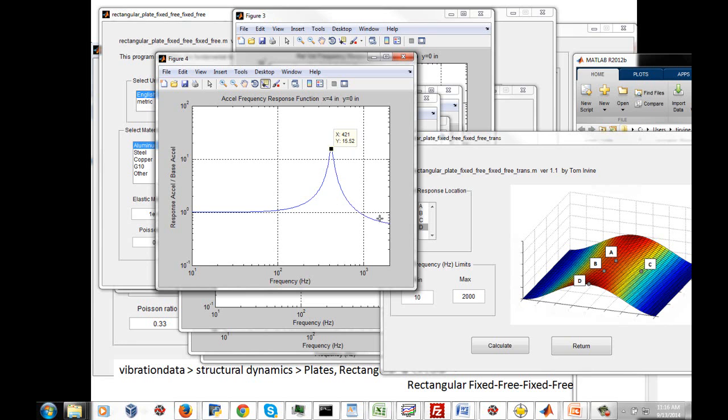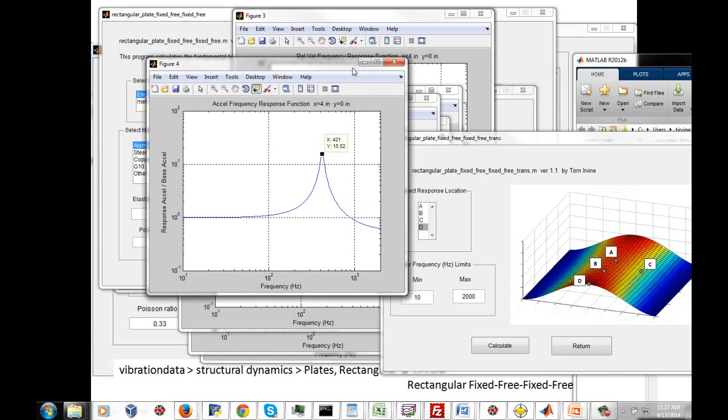Now some of that filtering is just an artifact because we only have one mode that we're representing. If we included higher modes, like do a Rayleigh-Ritz, then we'd see that there is some amplification occurring at higher frequencies. But we're going to be content with just a single mode because, for the most part, about 90% of the stress and pseudo velocity are going to be tied up in the fundamental mode anyways.